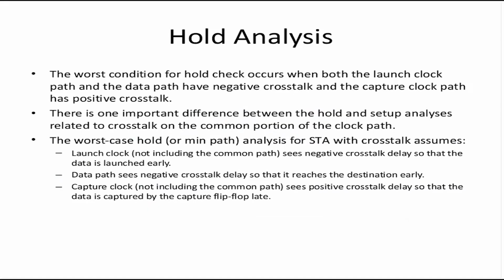Similarly for hold, the worst condition is when the launch clock comes earlier and the capture clock comes later. So the launch clock path and the data path will have negative crosstalk delay, and the capture will have positive crosstalk delay, right?